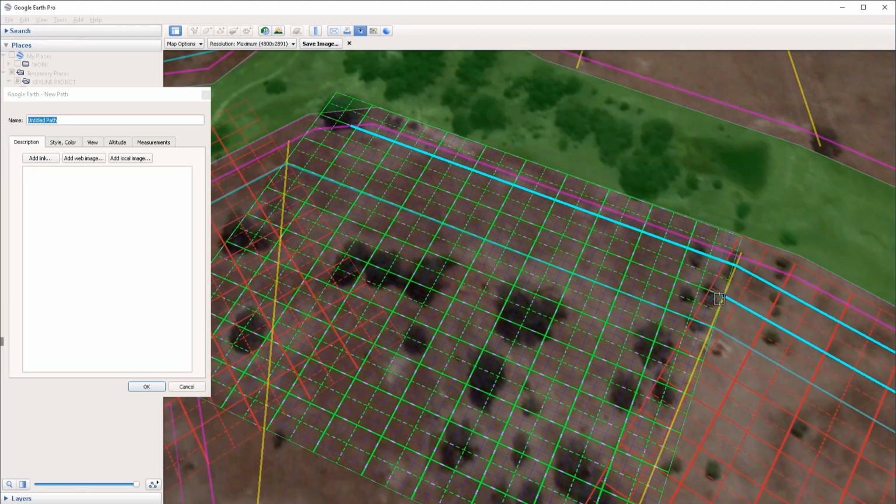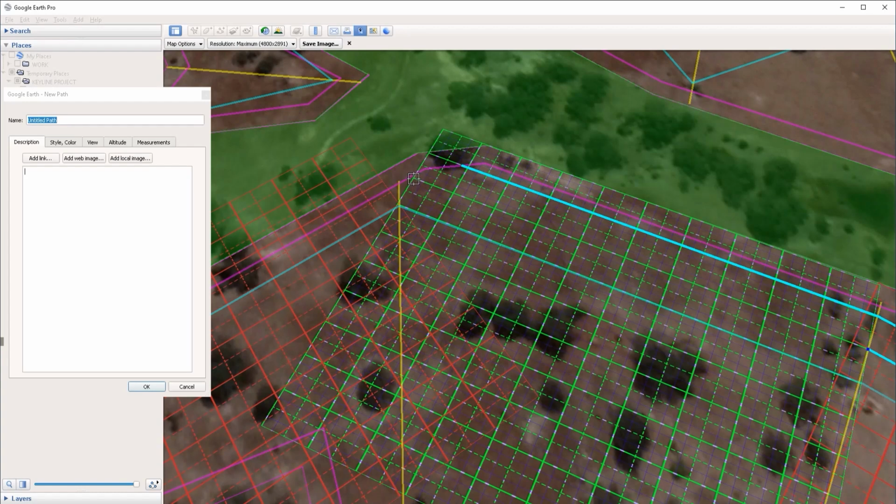This is why it was so important to have the angle of the guideline evenly split. If the angle was not evenly split and we just aligned the green grid to this segment and the red one to this one, then our rows were not going to be intersecting in such a clean way. The green grid may be somewhere else or right here, and then we will start having to adjust the line, and it would not give us equidistant spacing. So it is crucial to make sure that the lines of your guideline are evenly split by the trajectory line before you start overlaying these grids.